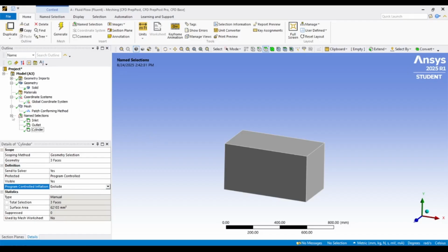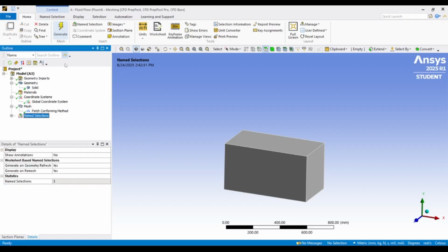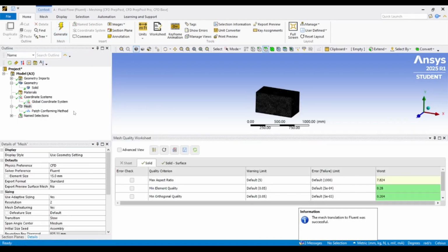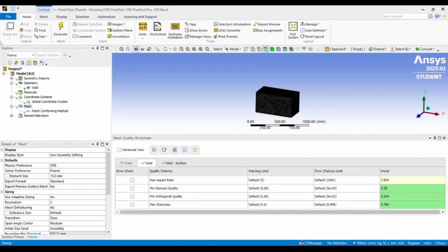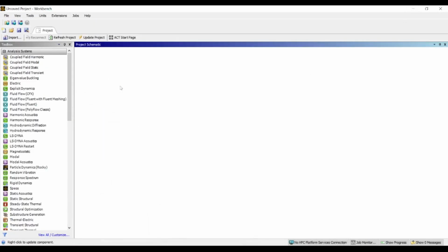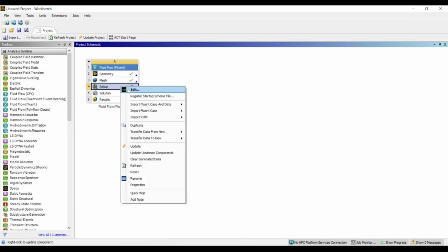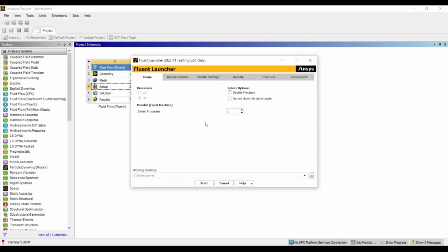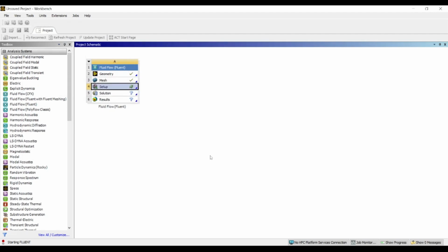You can export vorticity data over time to track vortex evolution or even compute frequency spectra using fast Fourier transform (FFT) analysis to quantify periodic shedding behavior. Another key part of the analysis is calculating aerodynamic forces, particularly drag and lift. In Fluent, go to Reports, Forces, and select the cylinder wall as your surface. Choose the direction aligned with the flow for drag and perpendicular to it for lift.